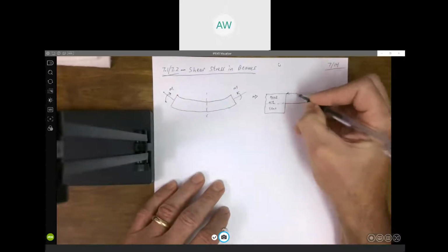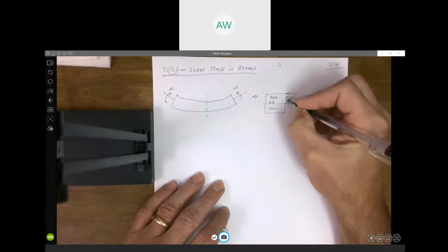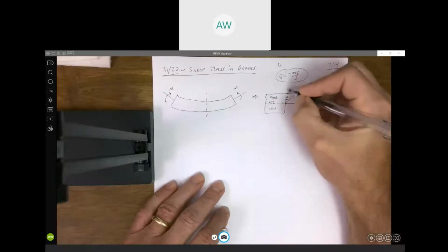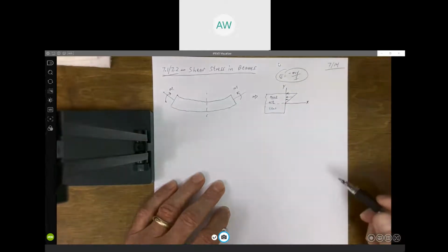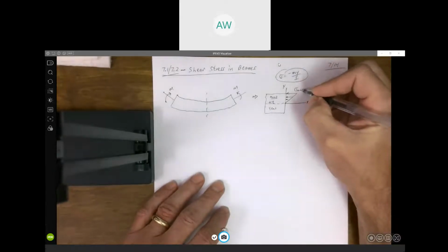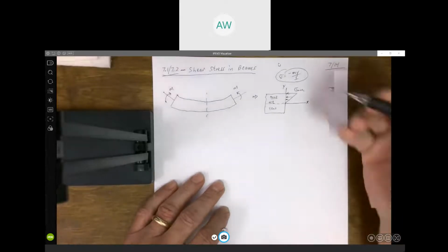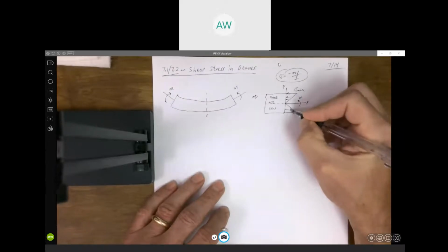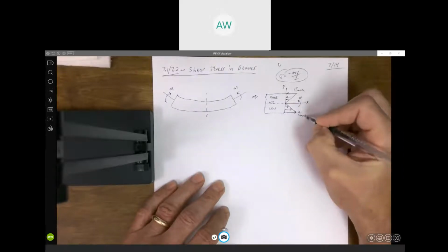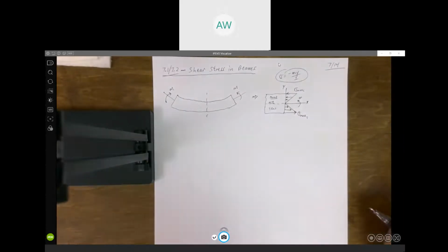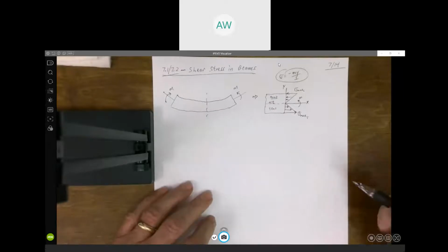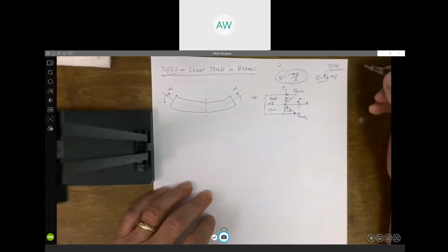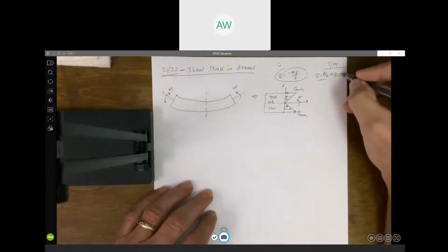And we saw this normal stress is linear. So, again, this is from sigma equals minus My over I, y being the vertical direction. So it's a linear relationship. The maximum compressive stress would occur at that top surface, again on the assumption we're bending it this way. And we'd have tensile stress down here below the neutral surface. Our maximum tensile stress would occur at that bottom. But we also know sigma equals P over A, so we get the equivalent force by taking stress times area.